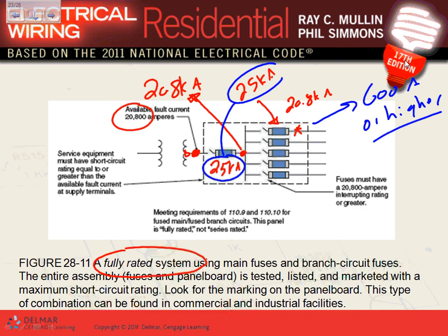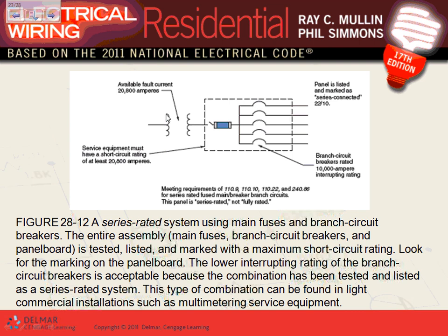And that will put you in a commercial industrial application. Any question about this? So that's basically where 600 amp or higher, rule of thumb, you can get a 100 amp fully rated panel if you want to. For 600 amp or higher, that becomes all the way up to 6,000 amp, fully rated system. Any question about that, guys? So everything is rated for the main, and the feeders and overcurrent protection devices are rated for the same interrupting value.